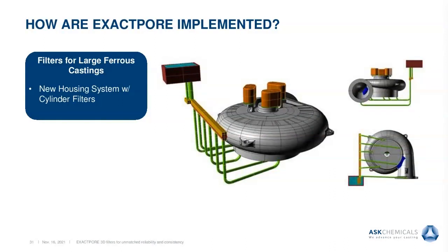An example of this is this 15,000 pound ferrous pump housing. Traditionally, they had used a series of filters horizontally applied to maximize capacity. Instead of having one filter, there are 10 filters in series to handle the 15,000 pound capacity of this casting. The metal is filtered adequately, but upon exit, it is allowed to cascade 1 meter down to the bottom of the runner system. When this happens, gravity overtakes the pouring system, and all the laminar benefits are removed from the filter.